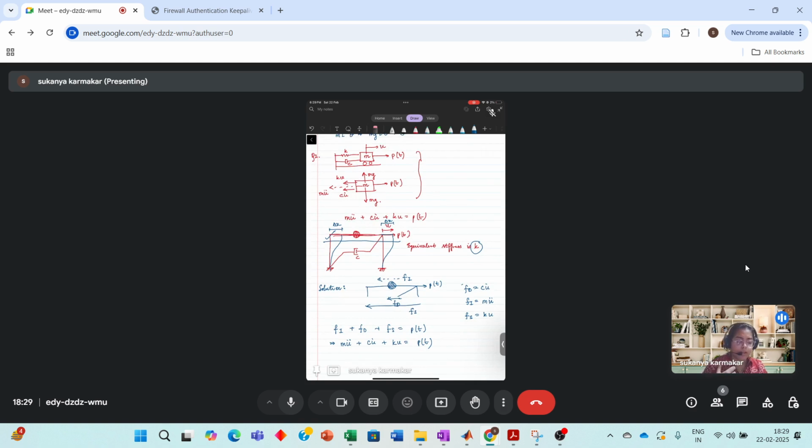The columns are inextensible, and we know the equivalent stiffness of the system K and the damping coefficient is C. We can study how we would figure out this K. Maybe I'll do that example as well. So we see that the spring dashpot mass system behaves, the equation of motion is quite similar to that of this plane frame. So any questions on this?